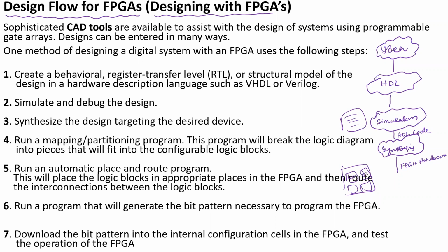So therefore, it will connect, it will take the lookup tables and you can implement your textual information in this form. Which type of lookup tables it can consider depends upon what type of FPGA you're using. That's important. Whatever FPGA you are taking, according to that FPGA's related resources, it can be considered, and that can be converted from your textual information according to that resource-related hardware.